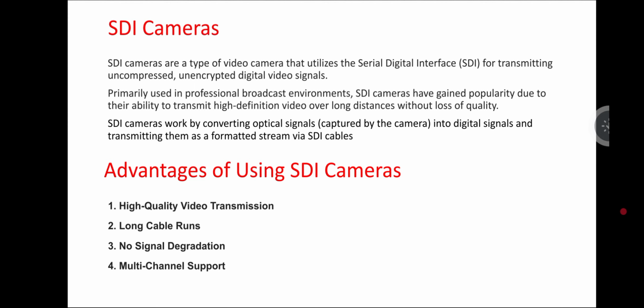And also we can say that SDI is a professional digital video standard developed for broadcast video. SDI carries uncompressed digital video, and it is transmitted over 75 ohm coaxial cables with BNC connectors. So this is the exact definition of SDI.